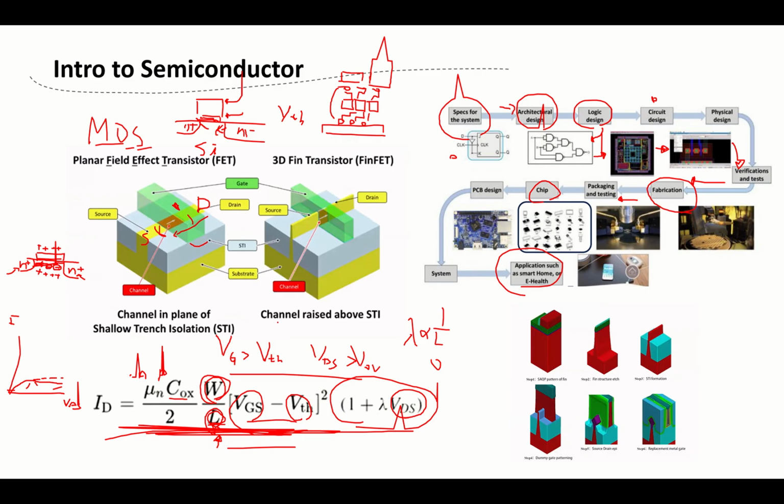Here's the time they use FinFET. In here, we increase the active area, which is the yellow one. So originally the width will be like this, but now we have a 3-dimensional structure, so the width will be 2 fin height plus 1 fin width. So we can largely increase the current without continuing to reduce the length, to prevent any leakage. So that's a basic overview of the MOS, and we'll talk in much more detail in the later slides.